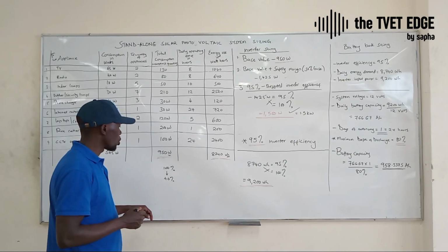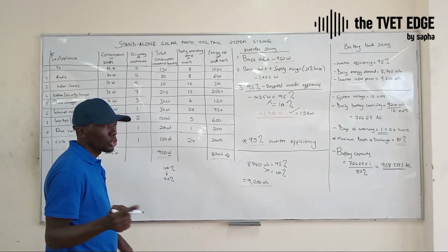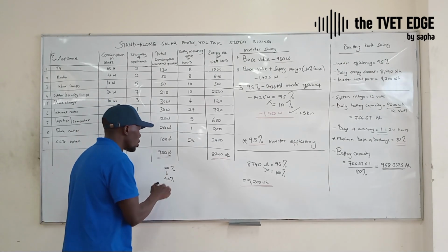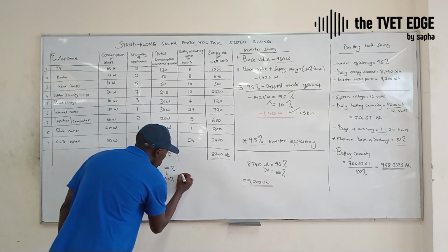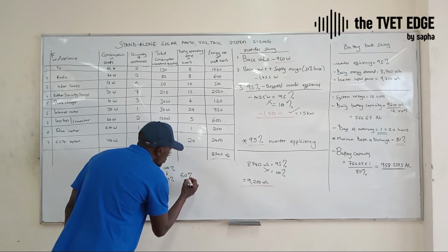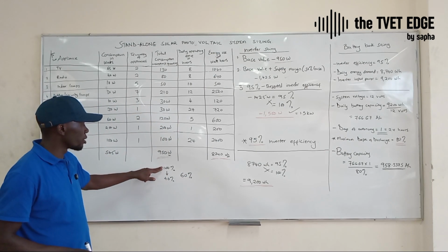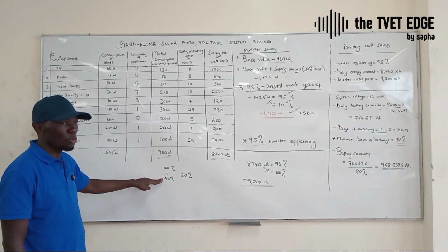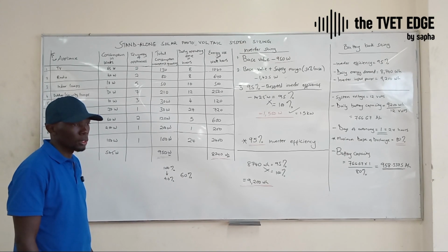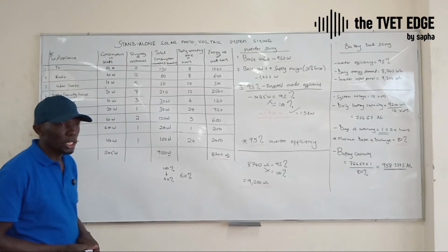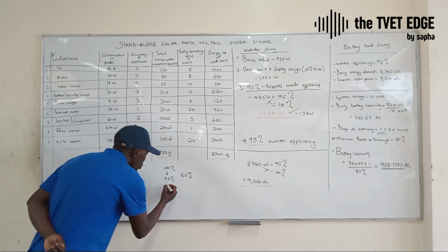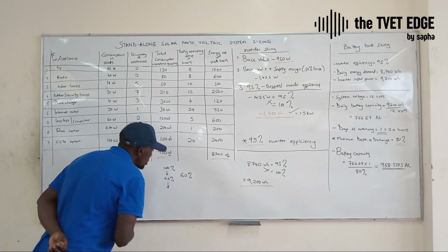8 a.m. tomorrow morning, your battery is at 40%. You start the cycle of charging it. So technically here, you've only taken 60% out of this battery. This is one evening. This is the next morning. You've taken 60%. The next morning, you start charging it back from 40%, and because we've sized our system correctly,